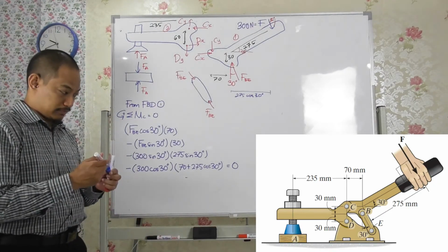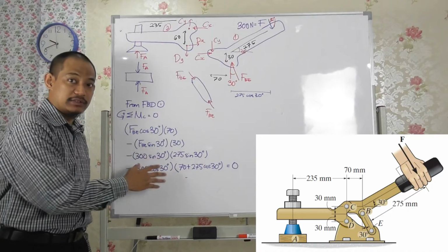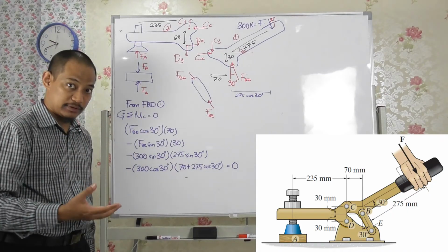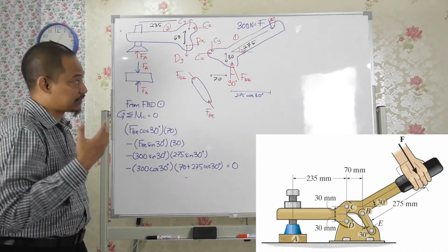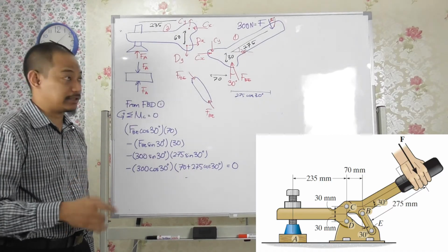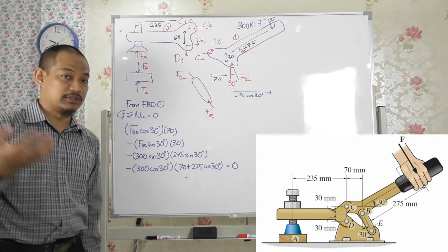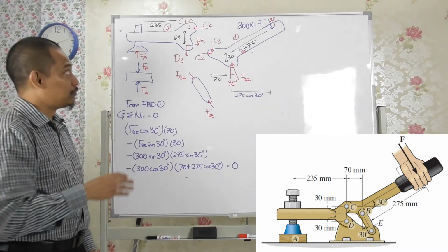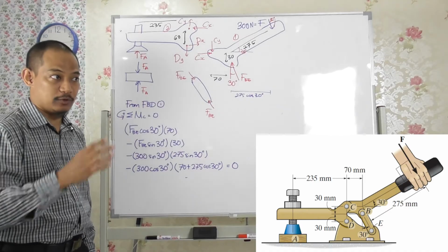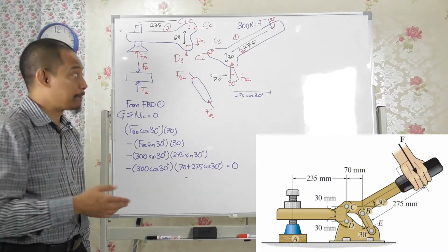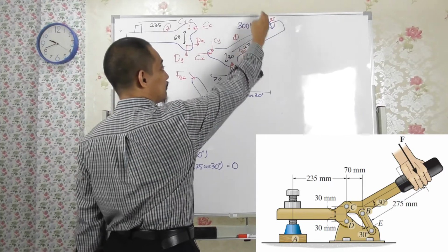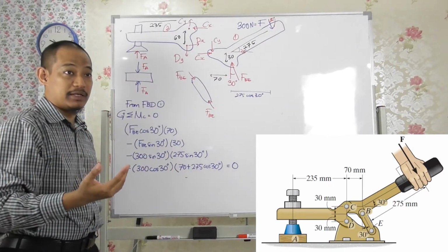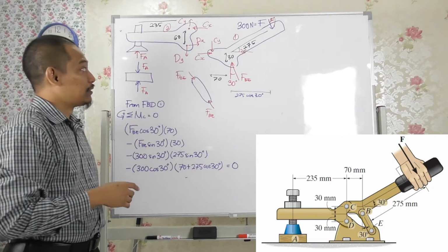Now, all of this is actually quite straightforward and not difficult if you understand what is going on, right? It's just force times distance. And normally, as we have learned from the earlier chapter, we resolve every force into horizontal and vertical. So for example, FBE, horizontal and vertical; F, horizontal and vertical; and then you just multiply by the perpendicular distance.